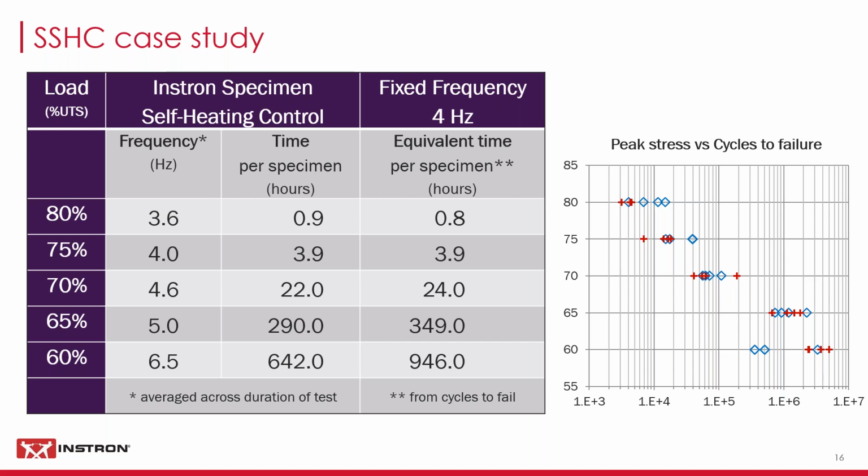Now, this is a slightly weird question. In certain circumstances, it can give you a more stable strain rate, but not completely consistent. This is probably a discussion for another day, and I'm happy to take it offline. If you look at some of the data that's out there, there are stages during a composites fatigue test where it undergoes much more heat deposition than others. In some cases, it might be three quarters of the way through the test, you start to get a level of damage accumulation, and the heating rate actually increases. So you have to reduce.